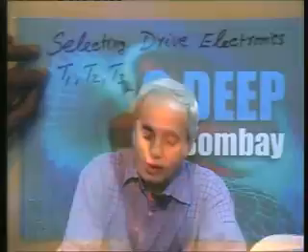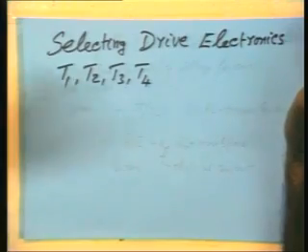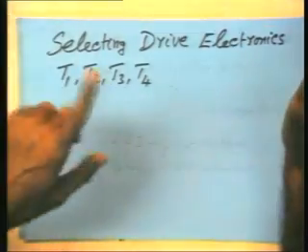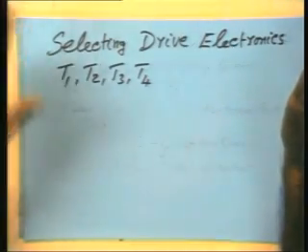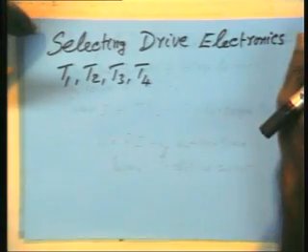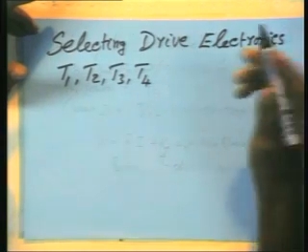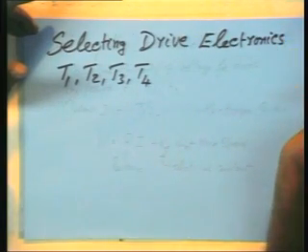Now what we have to do is, T1, T2, T3 and T4 are the torques in each of these period segments. T1 is for the acceleration, where the motor picks up speed. T2 is for the uniform velocity, where most of the time you are overcoming the friction load, unless there is another external load. T3 is the deceleration phase, where you need certain torque, and T4 is, of course, 0 in the example we had taken.